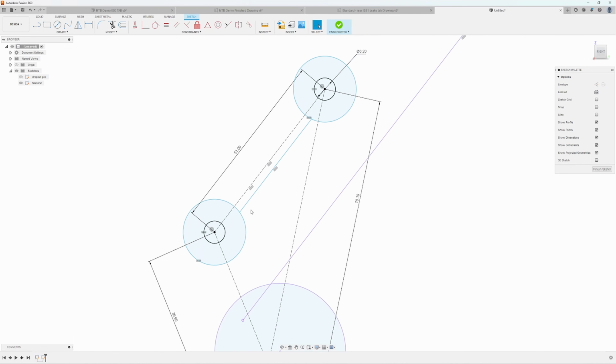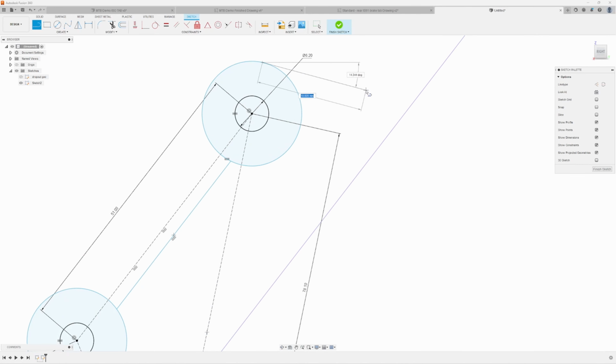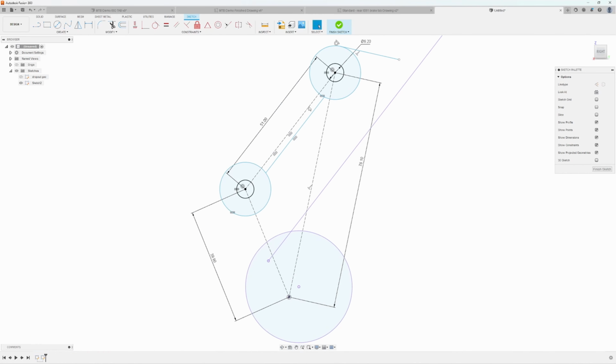and create a line. So I'm trying to make this tangent so it's a smooth transition. And you see here, if I move this line, you'll see the tangent constraint appear, and the line kind of snaps into place. So that's good there. And do the same for this guy. Tangent. And have it touch here.